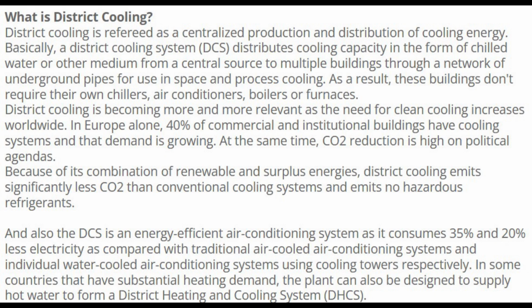emits no hazardous refrigerants. And also the DCS is an energy-efficient air conditioning system as it consumes 35% and 20% less electricity as compared with traditional air-cooled air conditioning systems and individual water-cooled air conditioning systems using cooling towers respectively. In some countries that have substantial heating demand, the plant can also be designed to supply hot water to form a district heating and cooling system, DCS.